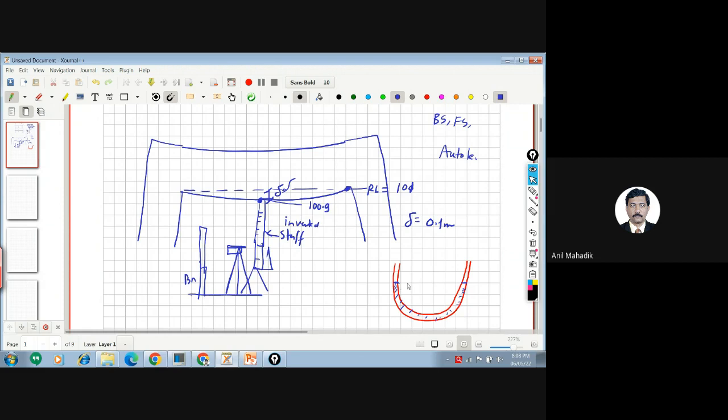So you can use this also. You can put any stick, or tape or staff, whatever you want, and you check the level here first, and then you check the level here. So you can do this at two places. You can put the level tubes like this, and for the same point you can measure this difference. So you can use the level tubes.